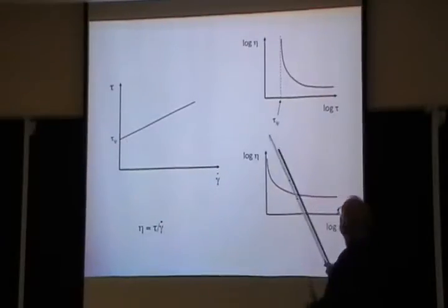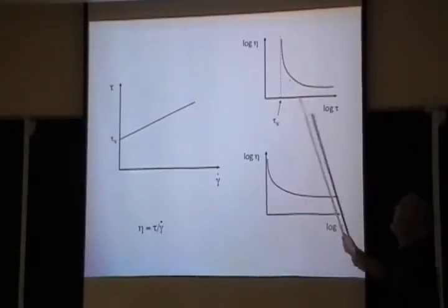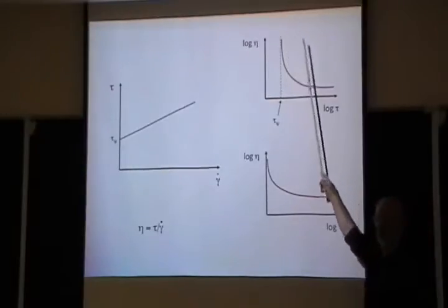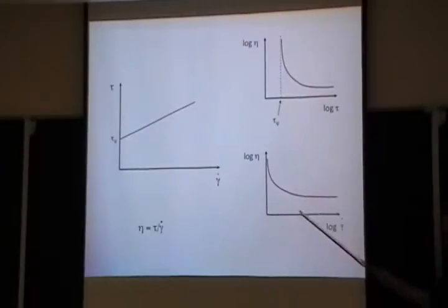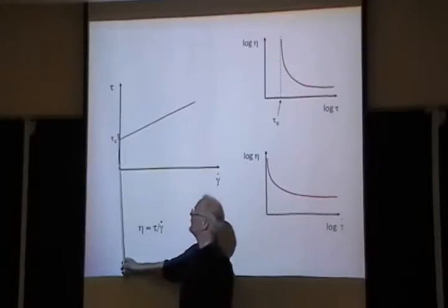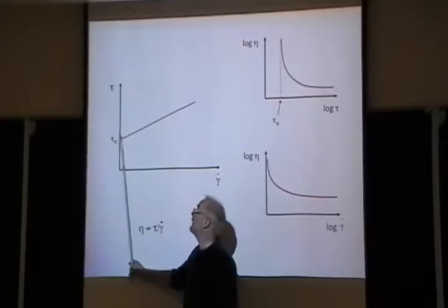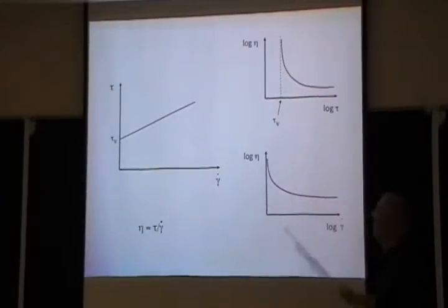And so then a curve like that will look like this. If you plot viscosity as a function of stress, where the yield stress would be where this diverges, and the same curve plotted in a slightly different way, namely directly like this, would look like that. Okay? Just familiarize yourself with that. The reason that this blows up is that basically this is almost like solid friction, right? Meaning just that there's no viscous component right near zero, so it diverges, and that's a yield stress.